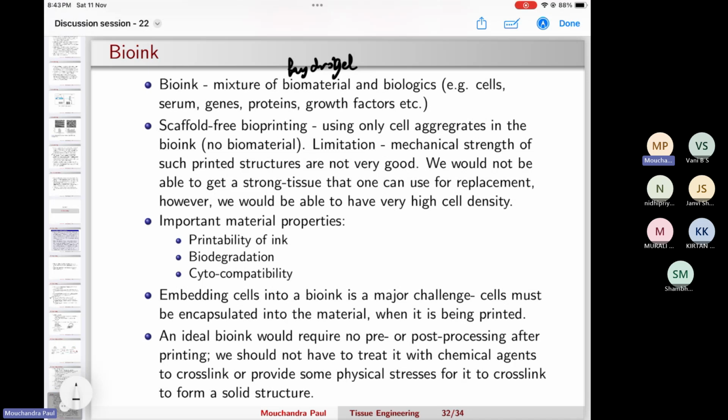And another negative point that I feel is the viscosity. The overall viscosity of the bioink will be like water, so it will never form filament kind of structures. You will have to look for a printing technology that supports the formation of droplets, and then using drops you have to assemble your structures.